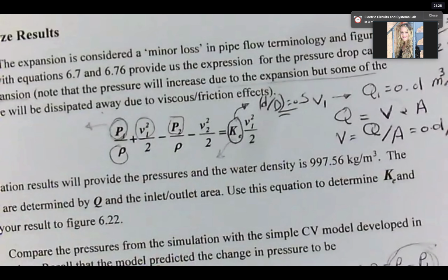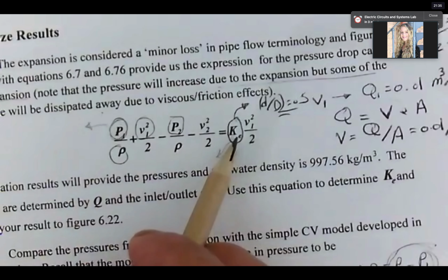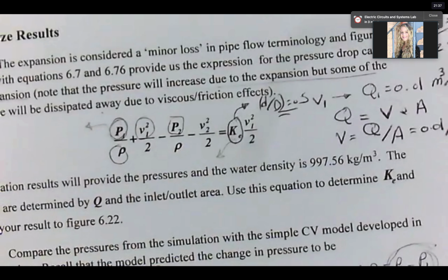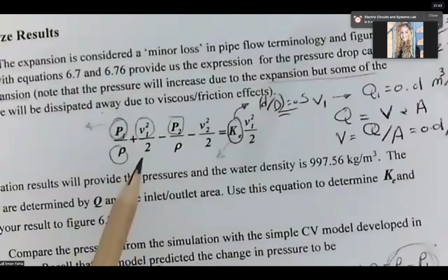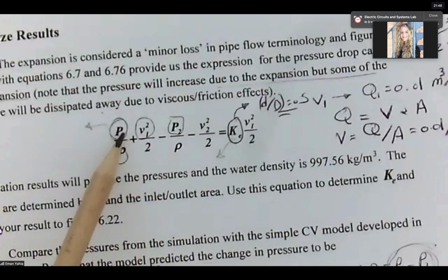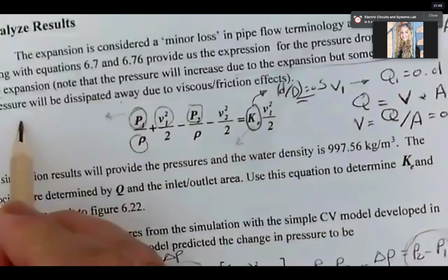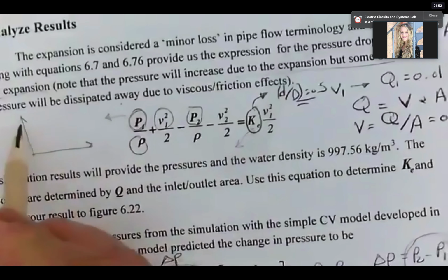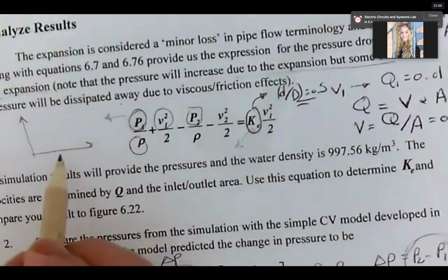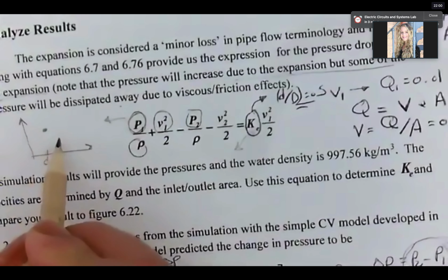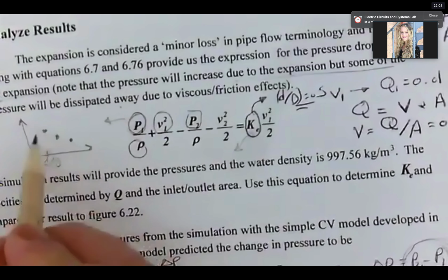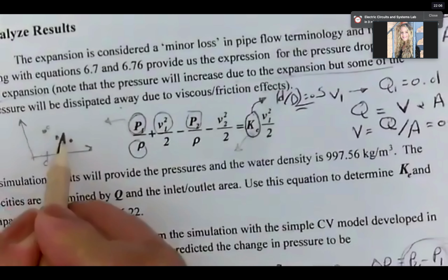Like if you get the output as the dynamic pressure, not the average pressure, all this can affect your answer. So what you're supposed to submit in the final report is your calculation, and you have to submit a chart, right? You were asked to compare K epsilon at different D over D, right? This is what he asked you, I think. So this is, let's say, what you get from the Moody chart. Your answer has to be very close.